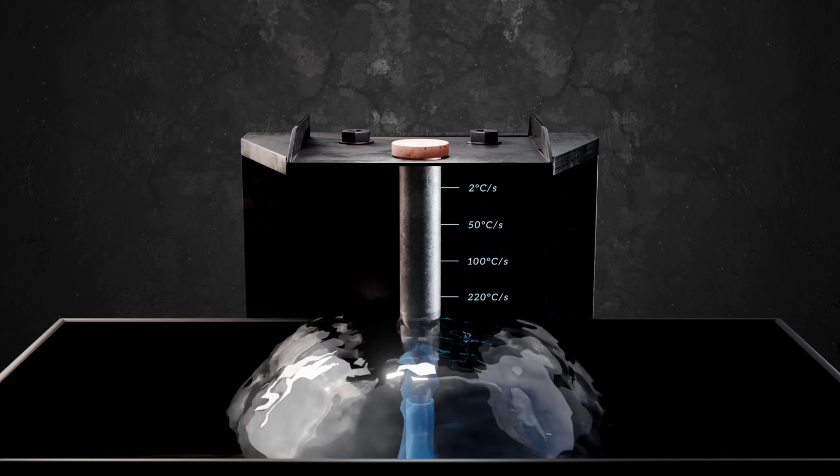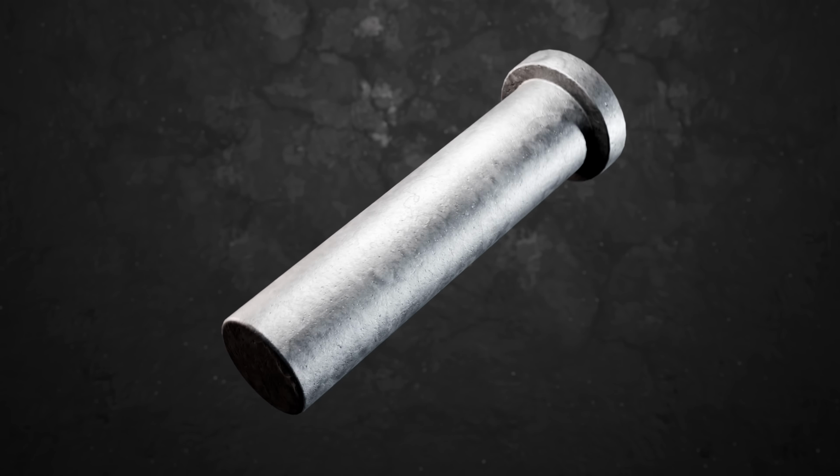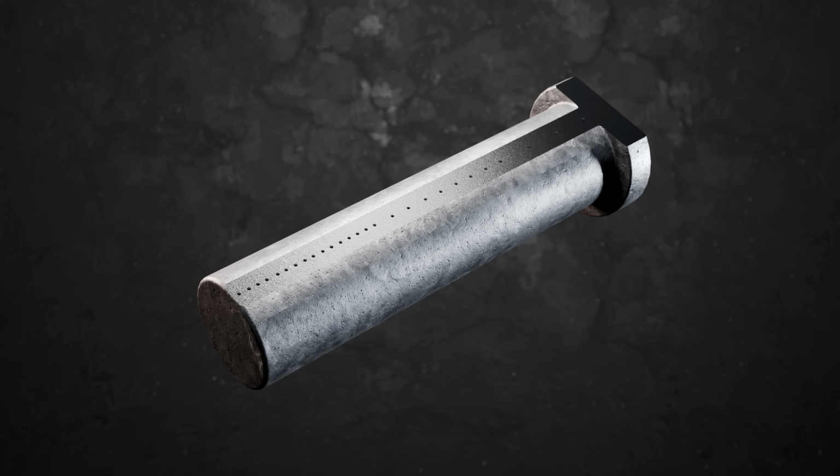A flat is then ground along the length of the sample, and Rockwell hardness measurements are taken at regular intervals from the quenched end. The results are plotted as a Jominy hardness curve.